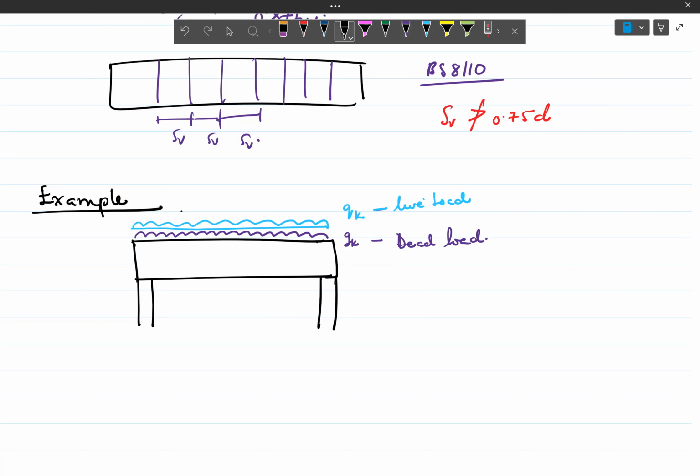Okay. So back to our beam. From the center of the support to the center of the other support is 6 meters. Okay. The width of the support, let's say they are 225 millimeters. Okay. 225 millimeters. And so there's a cross section.